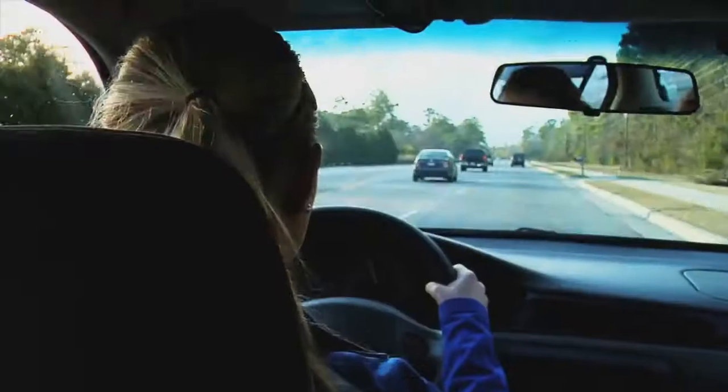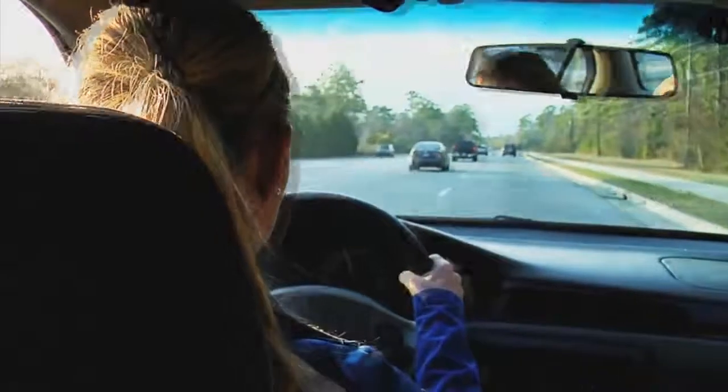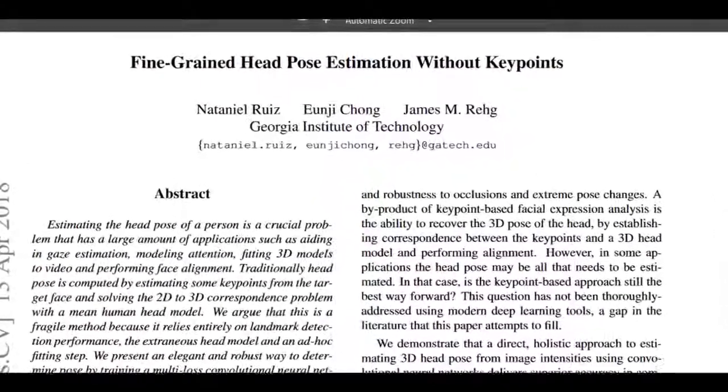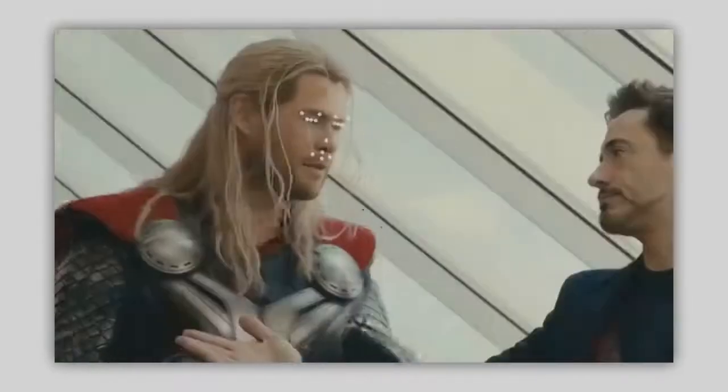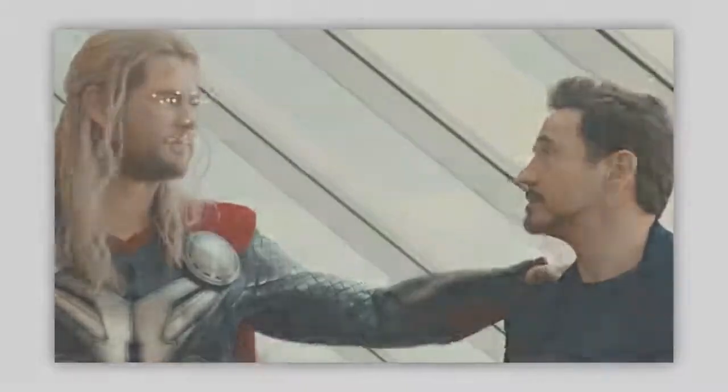The second model of the detection models takes a photo from the frontal camera and outputs the pose of the driver. By predicting the angles of the face in 3D space, the three predicted angles, which are yaw, pitch, and roll, help us tell if the driver is focusing on the road or sleeping, and so on. We used the 300W-LP dataset, which contains 61.1K photos, to train the model, and the AFLW2000-3D dataset to test the model.